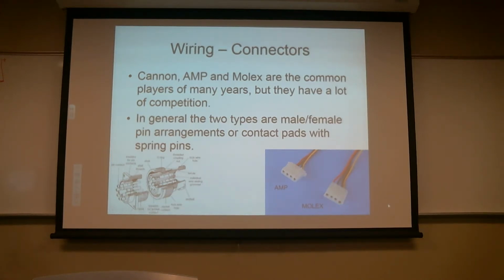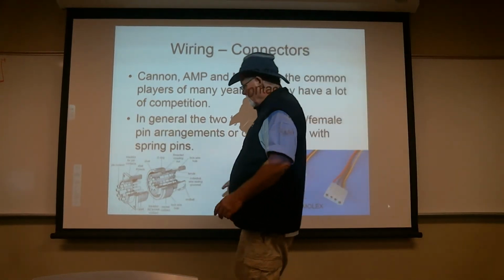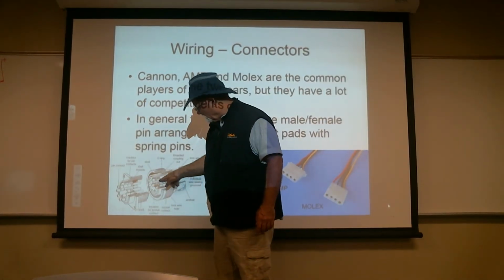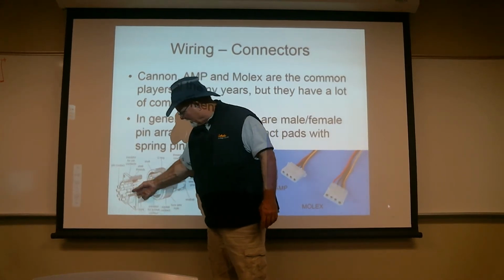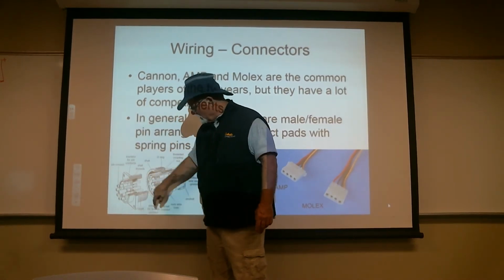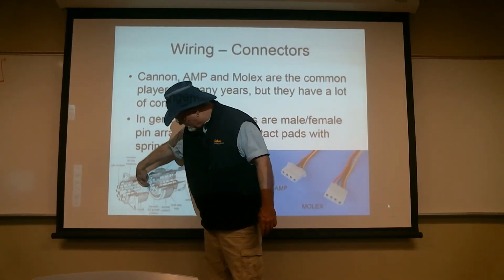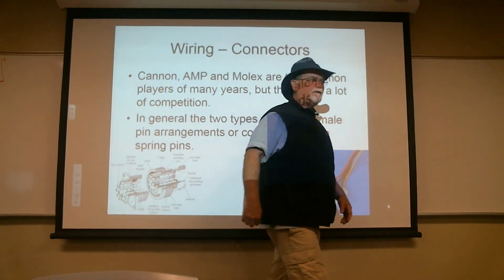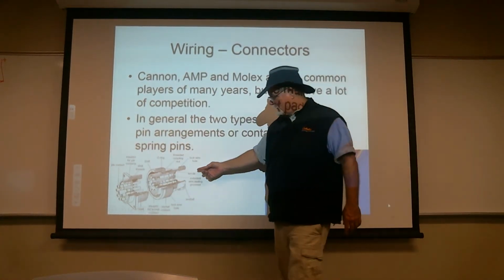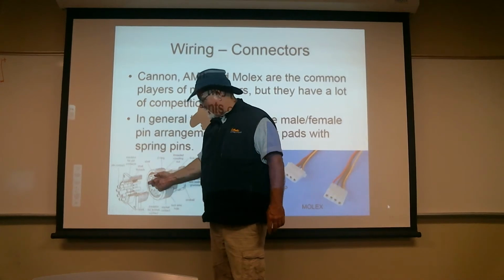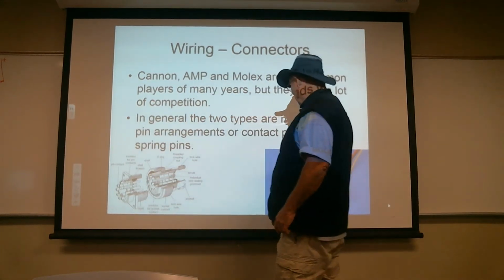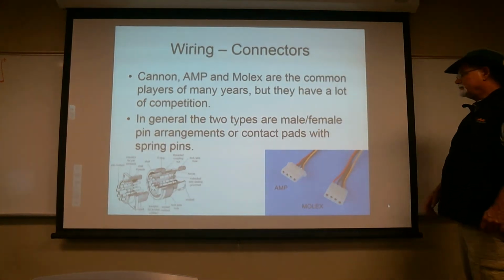The gender always is reflected by the pin, not by the connector. So in this particular case, you can see there's a male connector that fits inside a female housing, but it's the male pins here that go into the female. And the females in general are far more protected than the male.